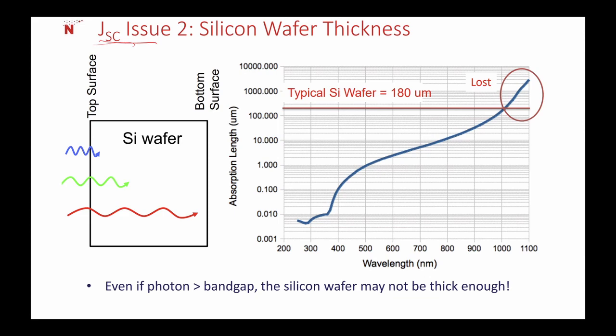So this is the silicon wafer. This is the thickness of the silicon wafer, which we say is 500 micron. This is the typical 500 micrometer silicon wafer. It is given as 180 micrometer because in solar cells thinner wafers are used. Whatever we use for other or research purposes, we can use around 500 to 525 micrometer.